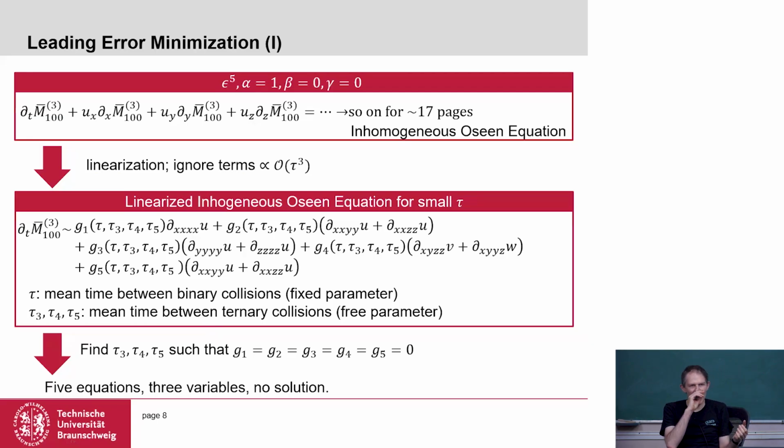And if to an Oseen equation you set zero initial and boundary conditions, this error term will actually disappear, unless it is an inhomogeneous Oseen equation, which means that it has source terms which are related to the solution of the Navier-Stokes equation. Which is the case, and which is the reason why this is only second order accurate.